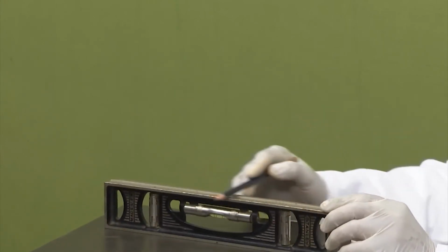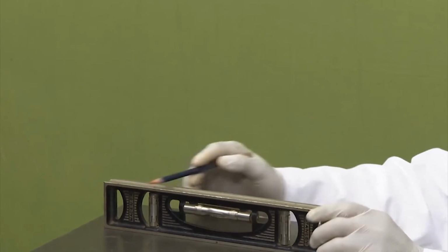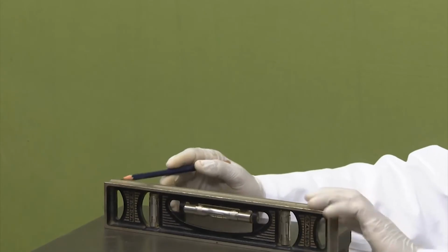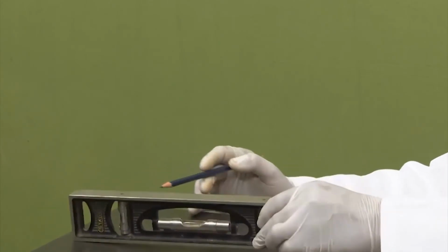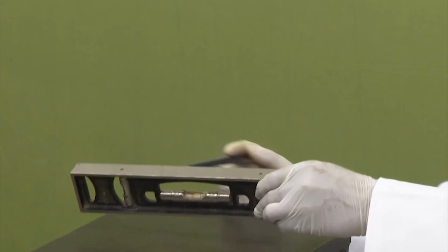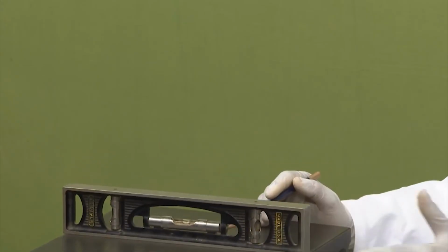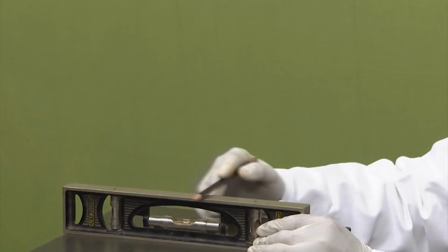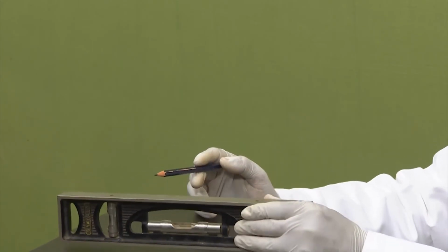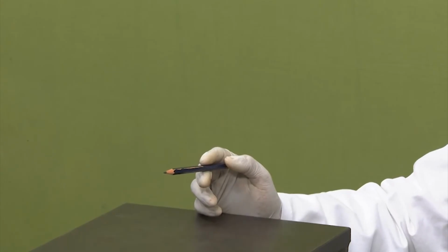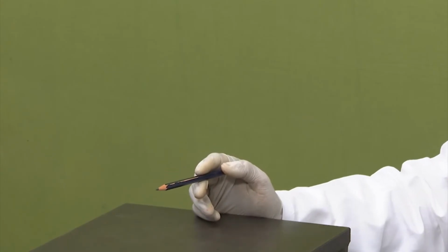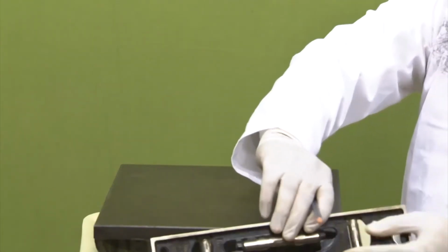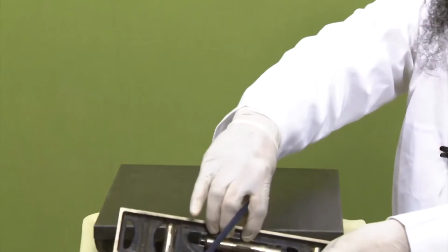In general, a spirit level is calibrated based on only one surface, and that reference surface is the one it has to be always used with. For instance, if I need to see a level from the bottom side and this is not the reference surface, it wouldn't be good practice to use it like this. Because this is the reference surface, we have to turn it upside down, and this reference surface has to be touched with the base to see the spirit level.